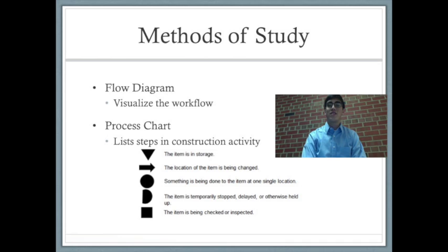There are 5 symbols that are frequently used in a process chart, but the circle and the triangle are generally the most important activities. The circle stands for a do operation, which includes both essential productive work and contributory non-productive work. Transport operations are required in almost every construction activity since material has to be moved around the job site in order to ensure easy access while in use.